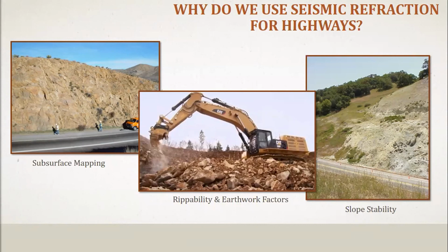However, due to scrutiny on budgeting for all phases of a project, geophysical studies are sometimes skipped to save on costs. This can lead to ballooning costs later in the project from overdesign, redesign, change orders, delays, and replanning. If design teams do not have all the information that can be provided, you can imagine they will need increased factors of safety, such as shallower cut slopes or increased slope layback, which can lead to more material being removed or more right-of-way to be acquired. Most of the actual cost overruns are in the construction phase, though. There they can run into unexpected subsurface conditions that can cause significant issues, such as full crew standby, equipment changes, or redesign. Geophysical studies can be the insurance against these unexpected conditions so that significant costs are not incurred during project execution.